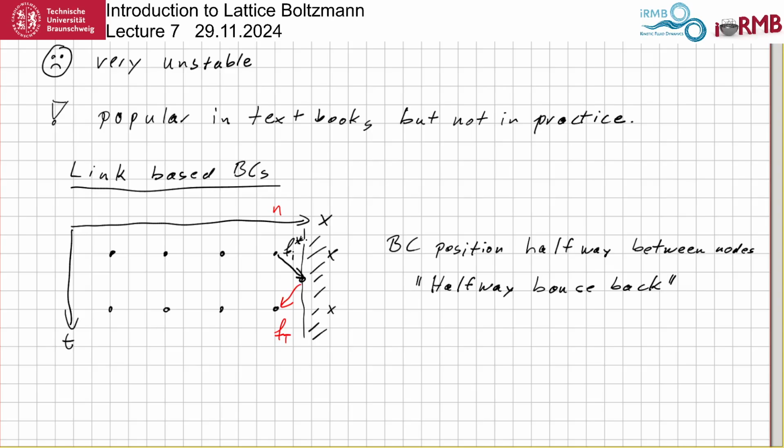if you look at this in very much detail in asymptotic analysis, you see that there is a small offset due to the stress that makes it not completely halfway. However, this offset is only of concern if the viscosity is very high, which again, we are in civil engineering, we have high Reynolds number, our viscosity is usually very small, so for us this is halfway bounce back. Even though, in theory, if you have a very high viscosity, this may be a little bit off. This is not a concern in civil engineering.